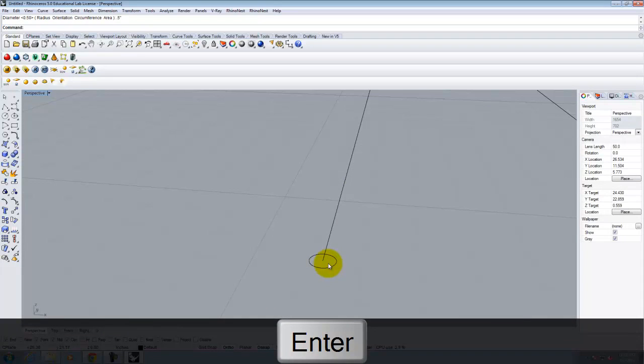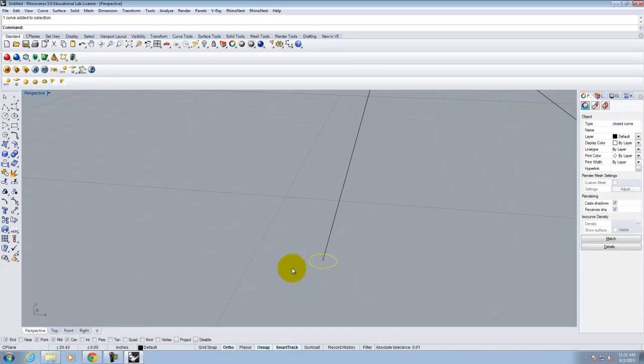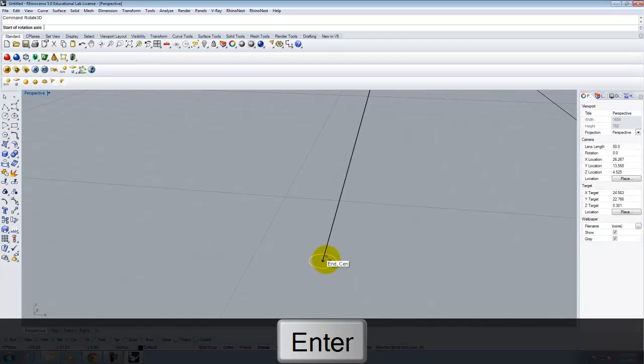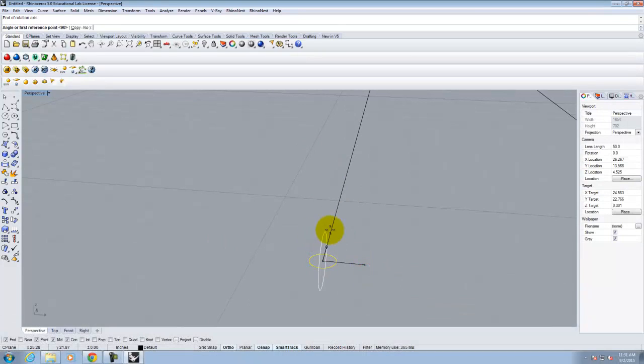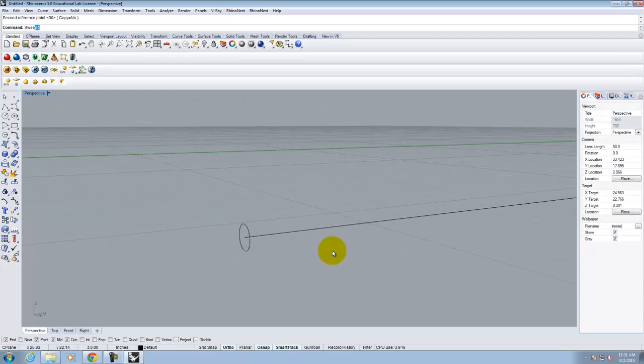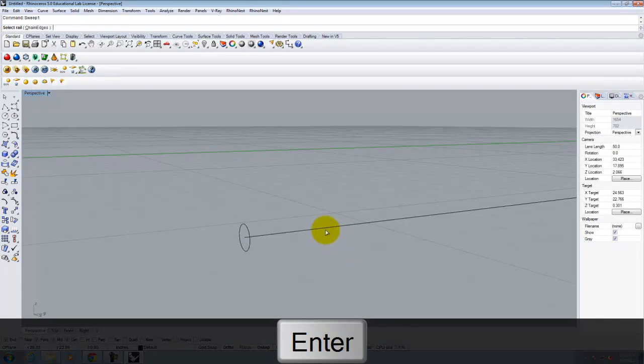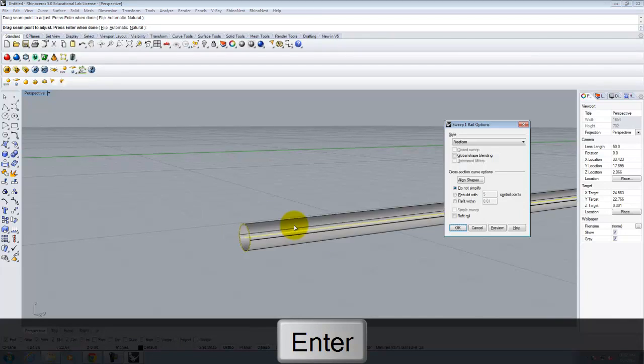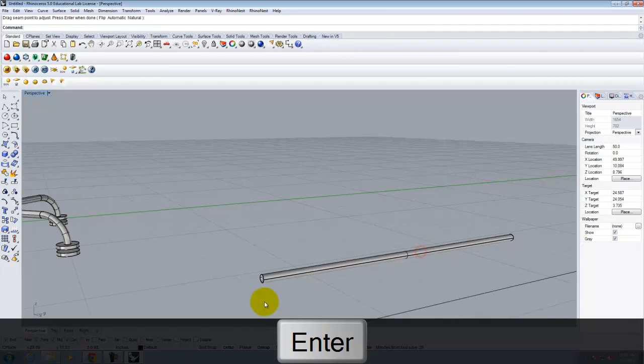And then I want to rotate 3D so that I can follow this curve. So let me go to rotate 3D. There it is. Right? And now I can do that sweep 1. There's my rail. There's my cross-section curve. And there's my shape. Okay?